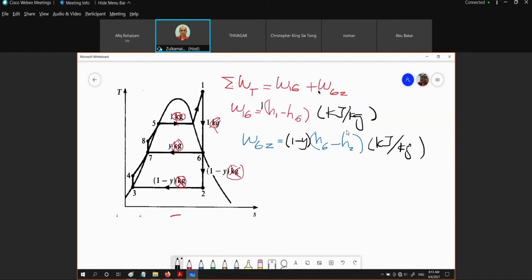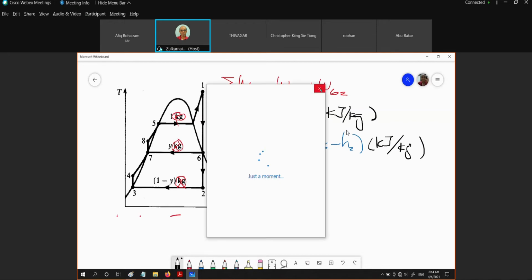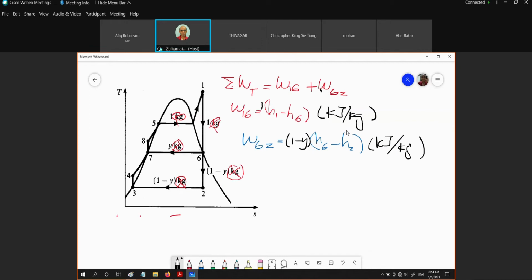So that we could get the W16, and W64 is still in kilojoule over kilogram, which is the intensive or the specific enthalpy, based on the change of specific enthalpy. Okay, so this is as far as the W16 and also the W62, which is involving the expansion process of the turbine. And this is what we could have as far as the work output or the gross work produced by this turbine. Okay. Now, if we look at the rest of it, our interest is the Q in.